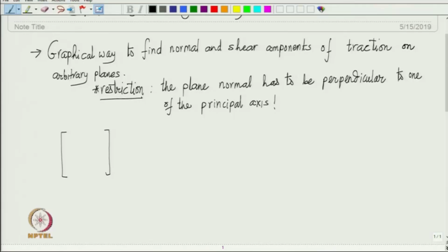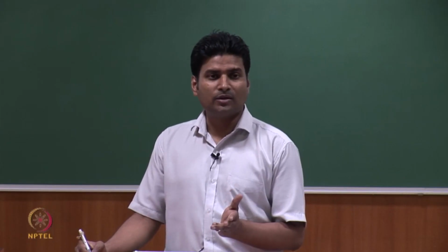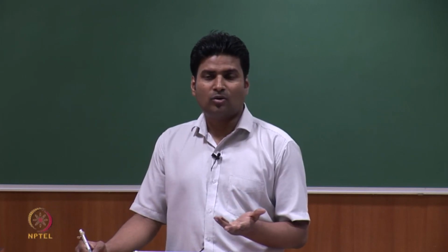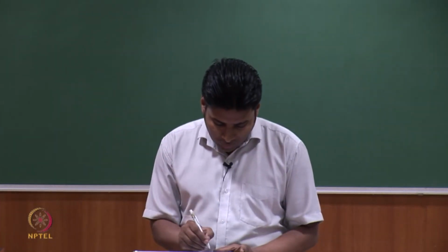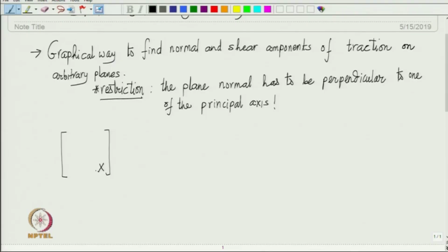If you write down the stress matrix, the third column is formed by the traction on the third plane, but that is the principal plane. So, it will not have any shear component, right, it only has the normal component, which means the third column would be such that the last entry is non-zero, but the other two are 0, is not it, because it is a principal plane.